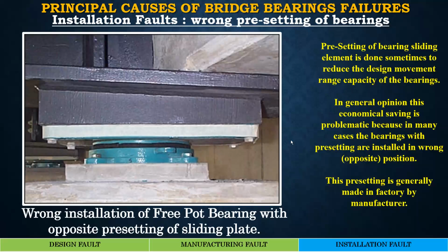So the suggestion is to avoid doing pre-setting. We need not optimize the bearing cost to such an extent. The additional cost due to an increased top plate dimension is hardly anything, and it is better to avoid pre-setting unless you are 100% sure that you will be able to ensure a proper installation of the bearing.